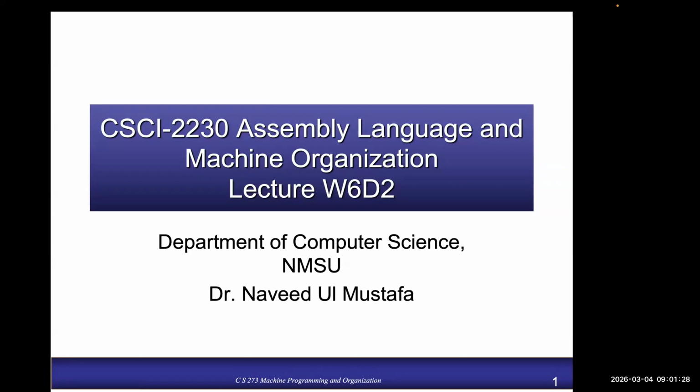Port C has 7 physical pins on the microcontroller. Other than that, we learned that to read and write data from each port, you need to know the working of three registers associated with each port, and those registers are the data direction register, the port register, and the pin register.